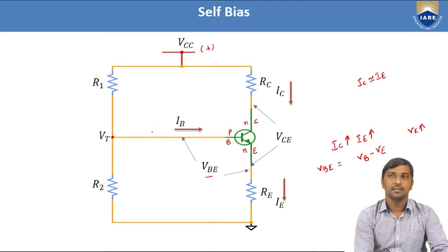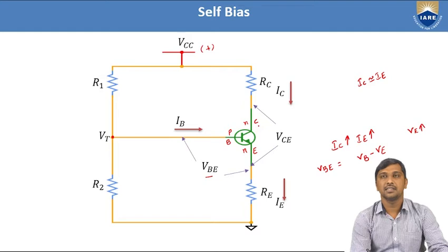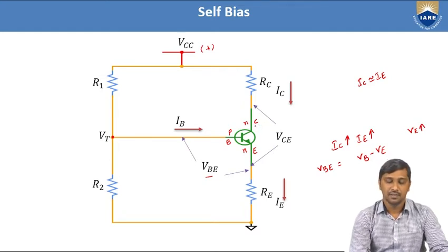Then this node makes your emitter base junction forward biased. Similarly, on the output side, we need to maintain the collector base junction in reverse bias. For this NPN transistor, the collector is made of N-type material. Hence, this N-type material is biased through a biasing resistance, the collector resistance, from the positive pole of the battery.